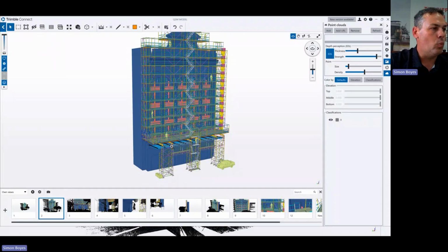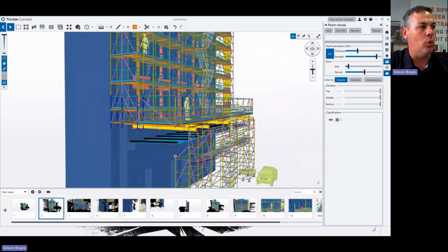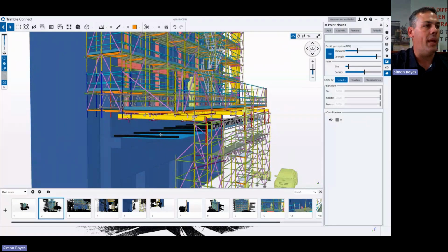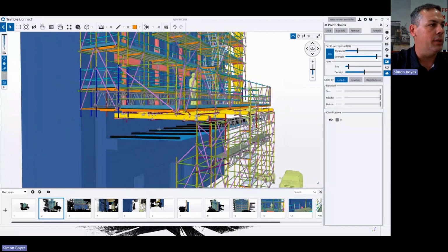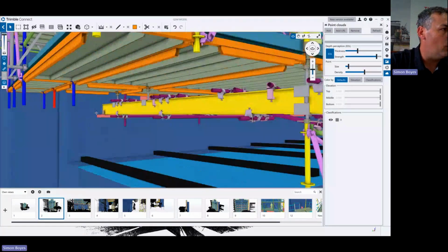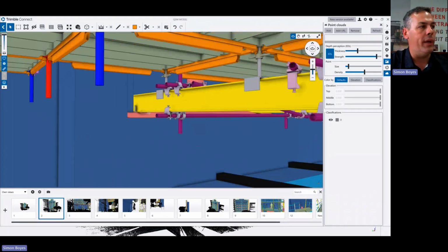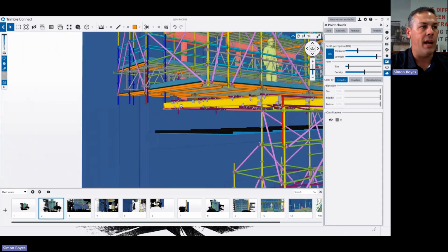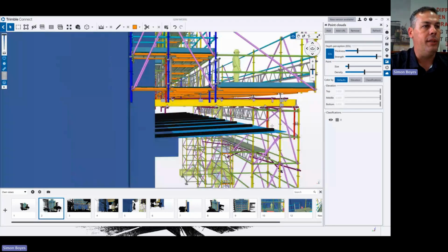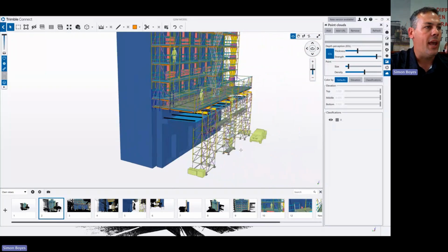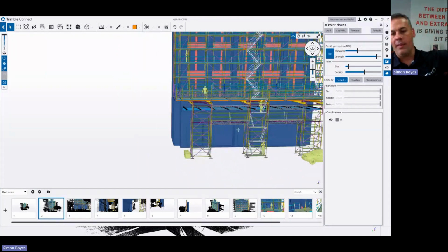So with this building facade down the bottom here and this glass awning, this was the real critical piece that we had to try to overcome. So what we needed to do was cut little wedges into the windowsills here so that we could crane the beams into position. So it was really, really critical that we knew exactly where those little cutouts in the windowsills needed to be before we started doing the scaffold installation. Because if we build this scaffolding on the ground here, and then these bays are in the wrong position, when we crane the beams in, the beams aren't going to line up with the little recesses in the windowsills. So this is where it gets really tricky.